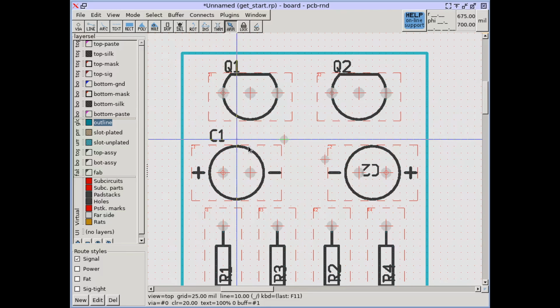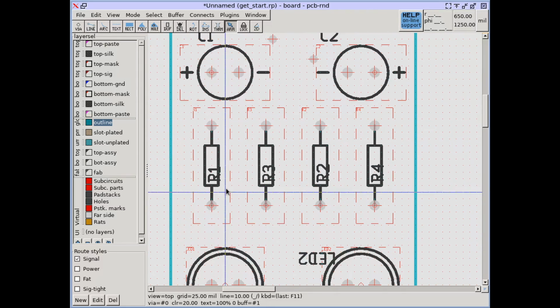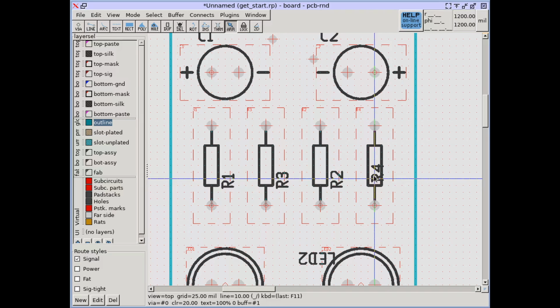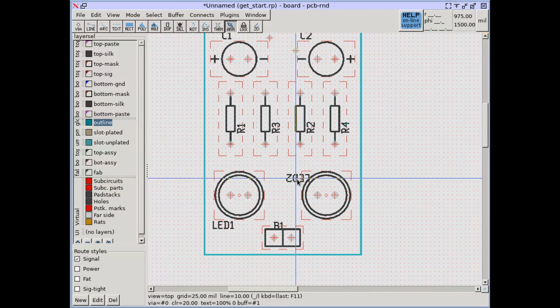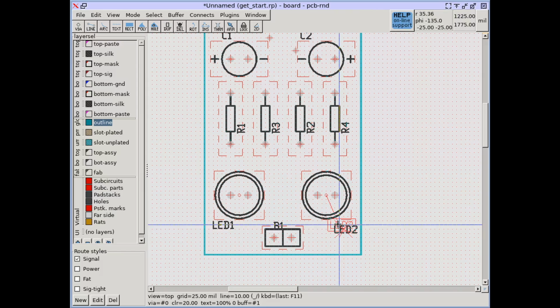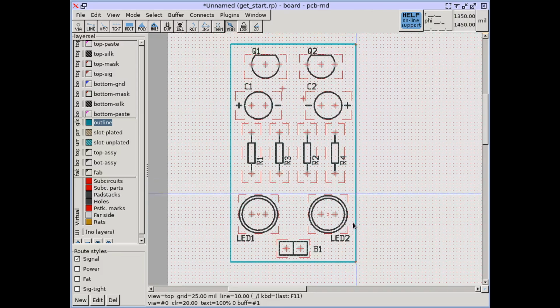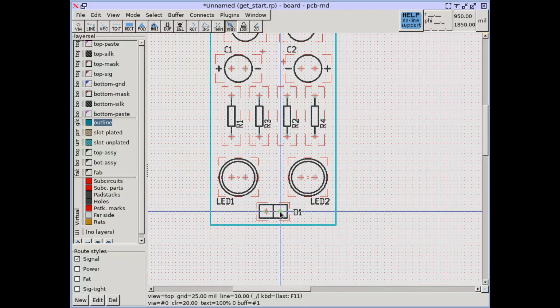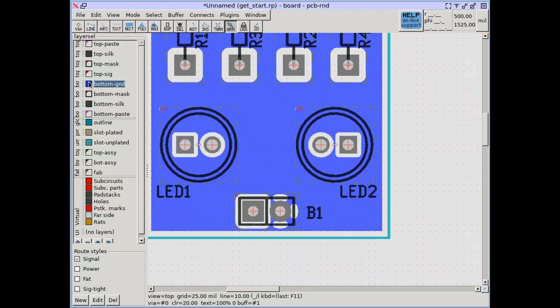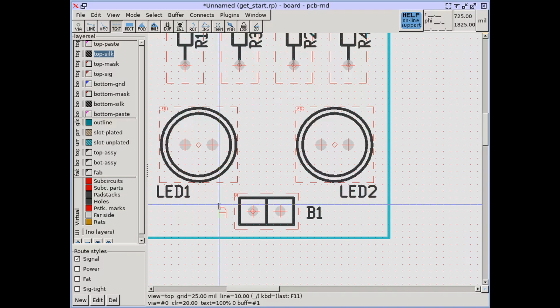Move the RefDes text out from under the subcircuits and use the Rotate tool to arrange them. It is a good idea to mark the positive and negative pins of the battery connector. The easiest way to do this is placing text objects on the silk layer. When clicking with the Text tool, a pop-up window asks for the text to be printed.